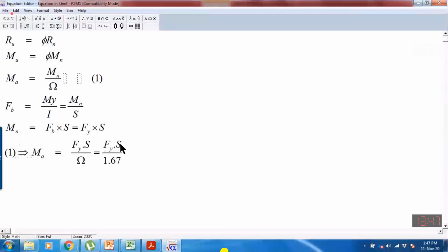I have just mentioned that the roof sheeting is continuously or intermittently connected with the purlin. So we are assuming that the purlin is continuously braced in the lateral direction, so there is no chance of lateral bending in the purlin.